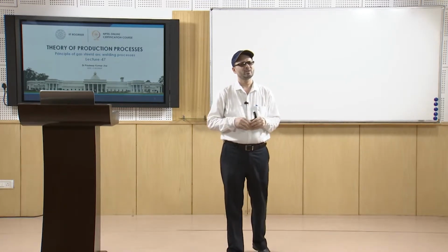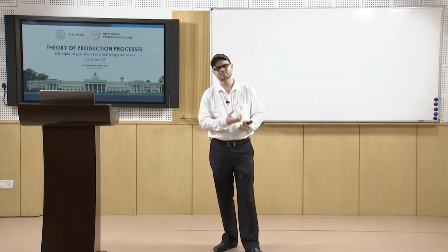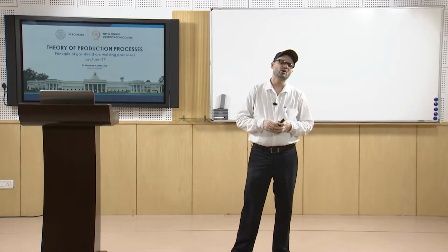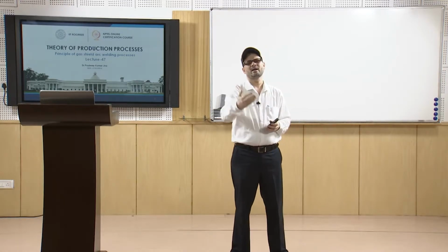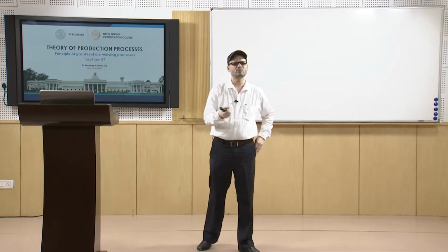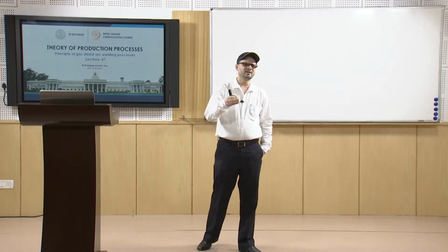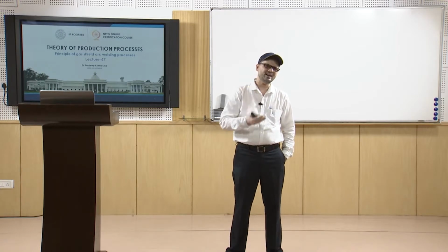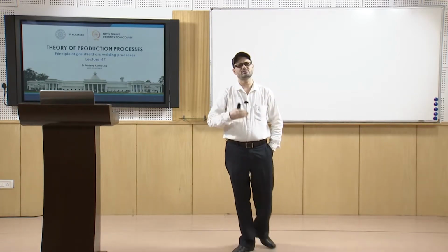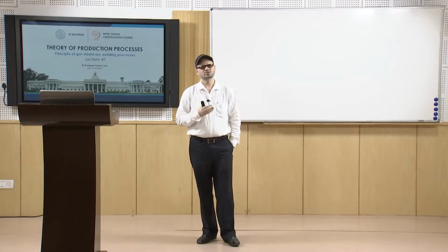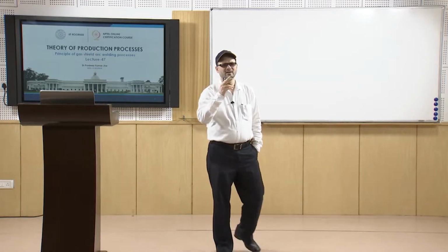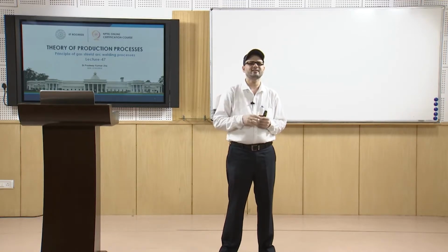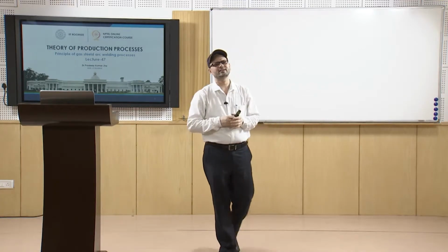It should not be kept in a wet atmosphere, so that it picks up moisture, because when you use it for welding, that may lead to gaseous defects. Similarly, when you use fluxes, there are chances of flux entrapment because of faulty welding procedures. So these are the advantages of using these shielding gases.